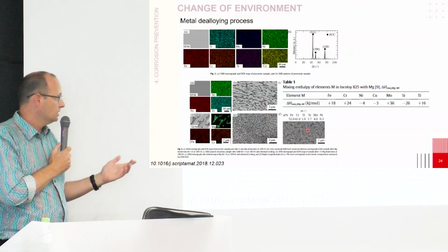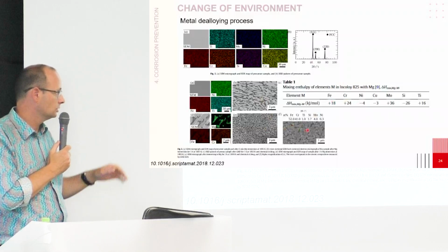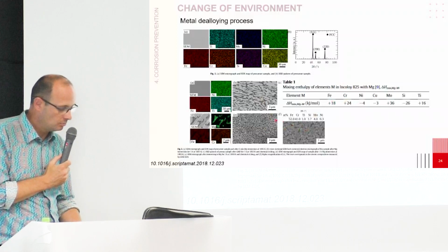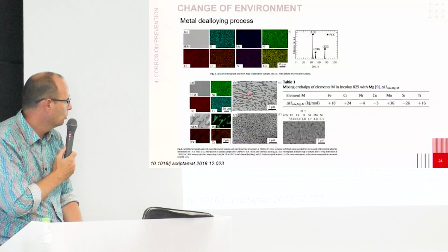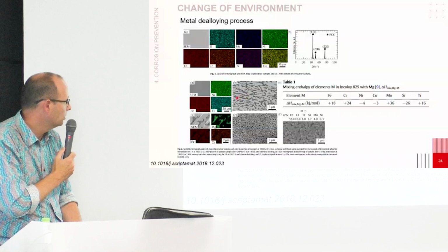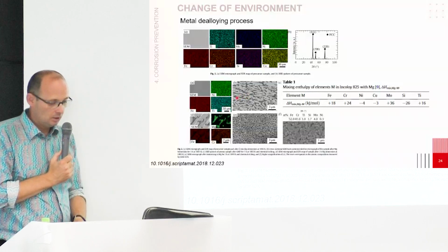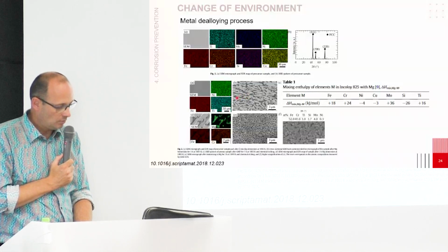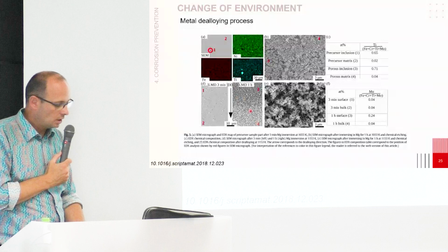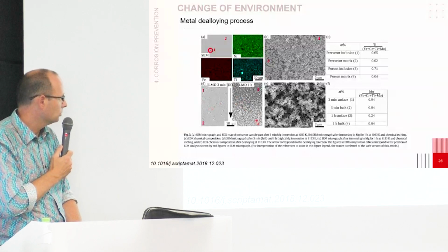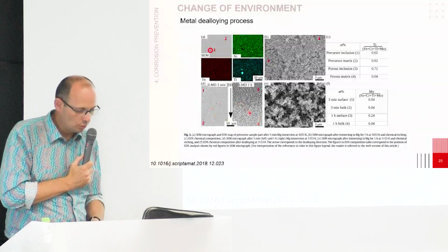When you have performed this, you have a new material and you need to stop by a solid state, where this microstructure, here in the micrograph, has the iron and chromium, and the black ones are the nickel and magnesium, which are mixing because of dissolution of nickel in the magnesium bath. This technology is quite nice because you can tune the microstructure of the ligaments, so you can get at the end a porous microstructure with a gradient of porosity in the volume.